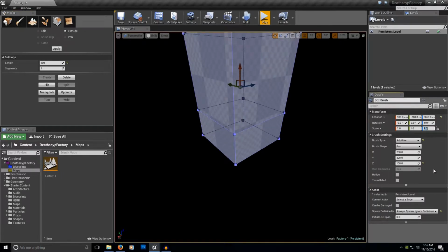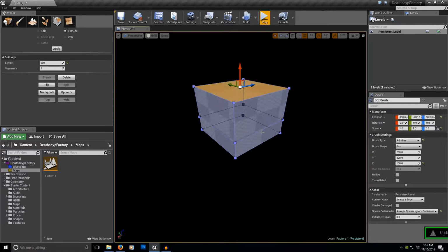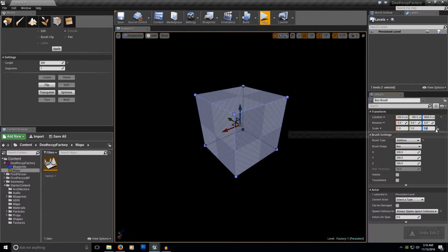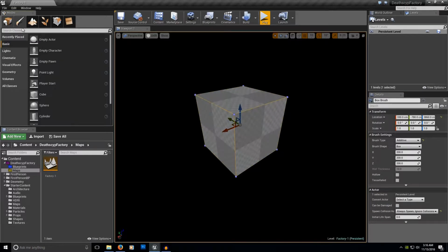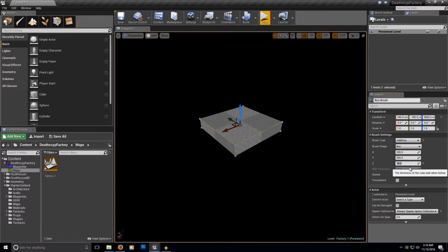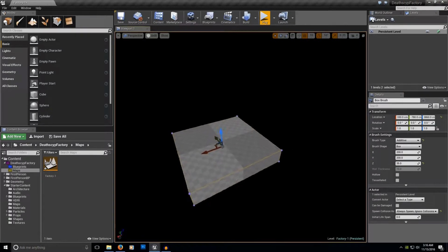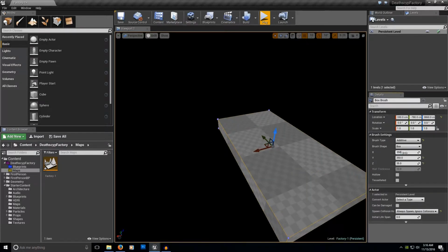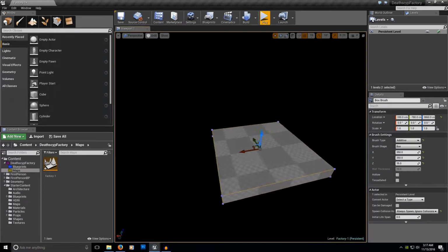Enter, and I'm gonna go back to my original state. So it's at 1. So I'm gonna go back over here to place, Shift 1 if you're using the hotkey, and we're gonna grab the Z axis and we're gonna put it to 35. So we're creating our floor right now. In the y-axis, I'm going to go 350, and the x-axis 350. I'm pretty happy with that.